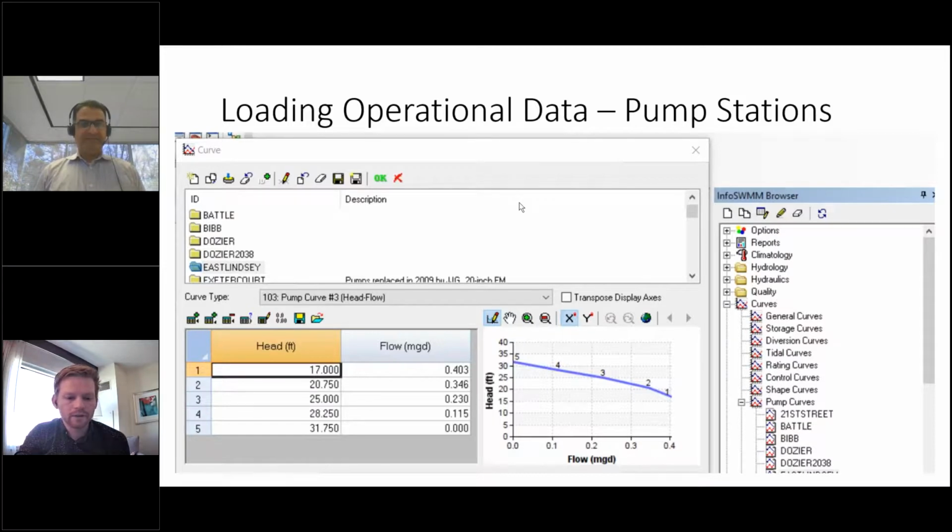However, within the toolbox of ArcMap, and I would assume there's a tool within ArcGIS Pro as well, there is an option to convert a CAD data set into a geodatabase. It's called CAD to geodatabase. I don't know how clean it is or how well it converts that, but it does look like there is somewhat of an option to be able to do that kind of thing.